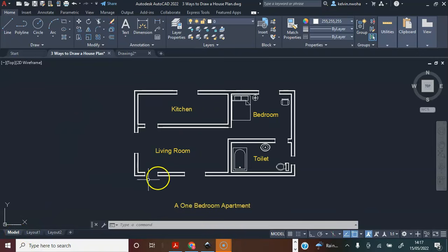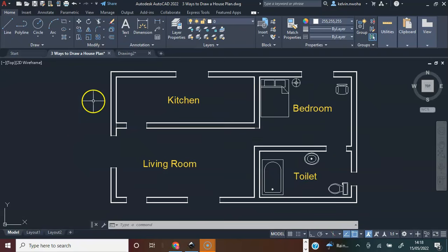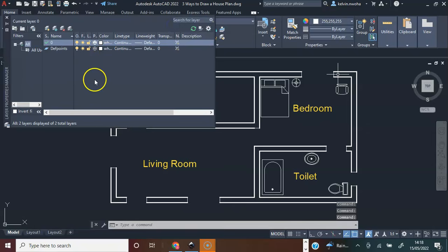Now, instead of having all these labels together with the equipment in the house, which will be interfering with the dimensions of the house plan, instead of having all this together in one house plan, you can use the layer property to arrange and manage everything inside that building, which we are going to see in a separate video.